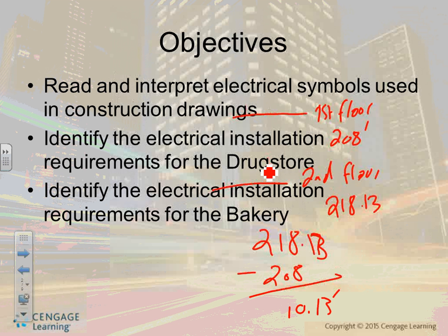Guys, my friend, in Revit, the arrow is so important because you will be drawing sections in Revit. And someone will say, I can't see what you want me to see because your arrow is pointing the other way. Look how nice Revit is. You can flip the arrow. You click on the arrow, it was pointing this way, now it points the other way. You see this way now, or this way.